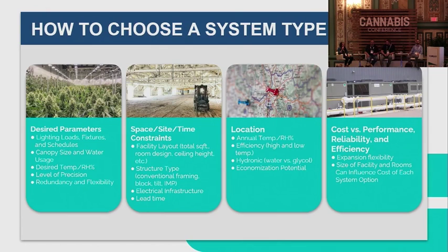Yeah, so those units, you need at least one per room, and they're fairly large, so they either need to go on the roof or they need to go around the exterior of the facility, and a lot of these facilities are on a street or have a parking lot there, and their roof is old, or they just don't want to pay for that structural component of having equipment on the roof. It can get very expensive, very fast. It's a structural upgrade to reinforce the structure in an older building. Yep, so those are some things that we can put together pretty quickly to see if it's a feasible option.